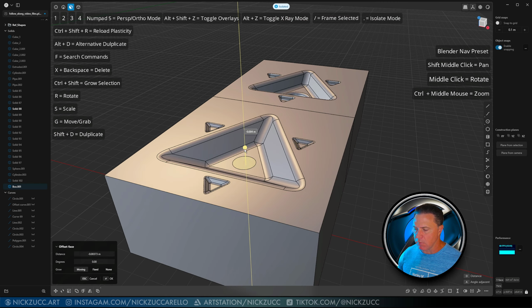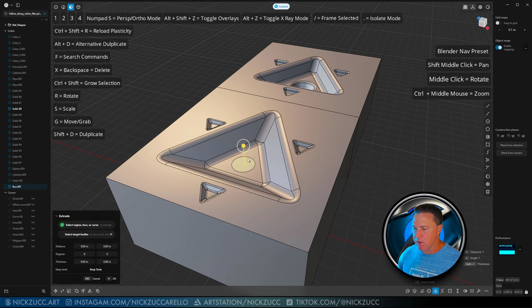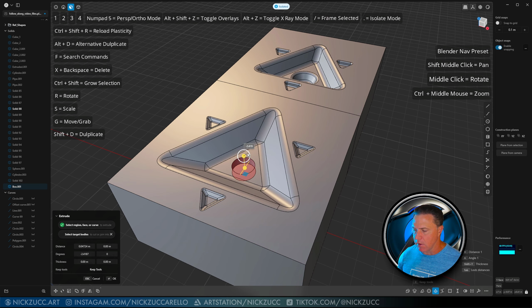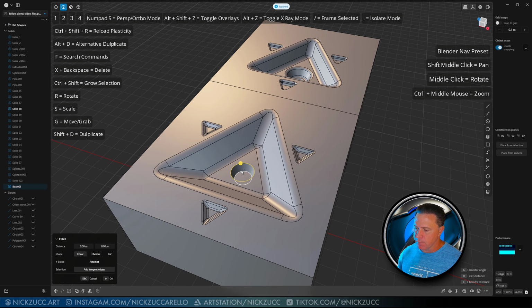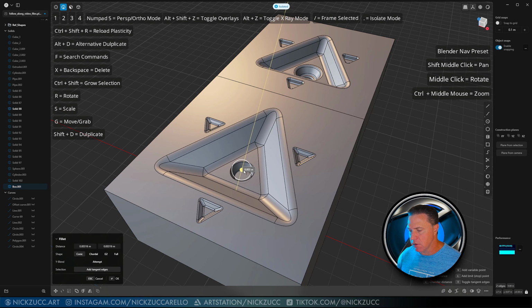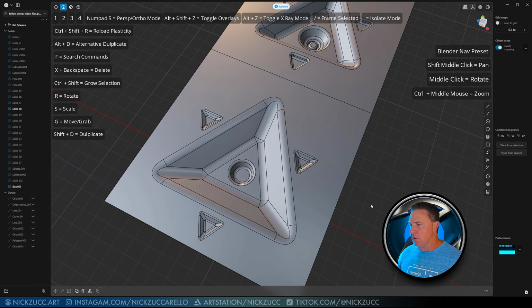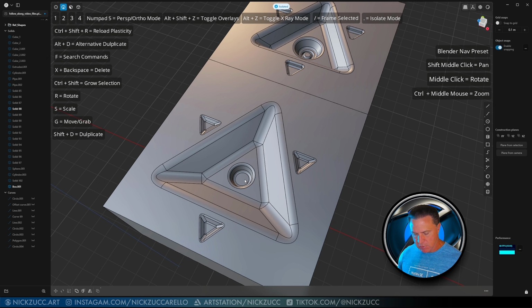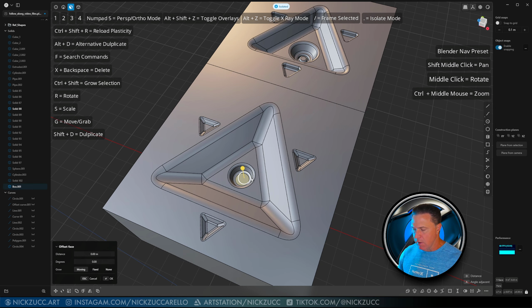I'm going to tap 3, and I'm not going to drag straight down. I'm going to select E and then push down. And then I'm going to go ahead and taper in like that. Tap 2. And then I'm going to hold down Alt and Shift so I can select multiple edges, just like that, and drag out right about there. And the next part that I did on that, I took this face here, tap 3. If we do O, we can drag this in, and I might be snapping to some things. There we go. So that looks like it'll be pretty decent there.